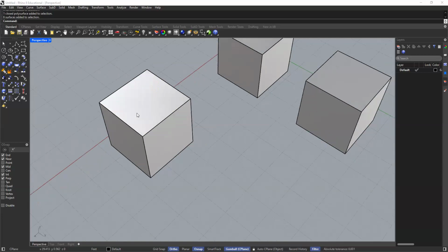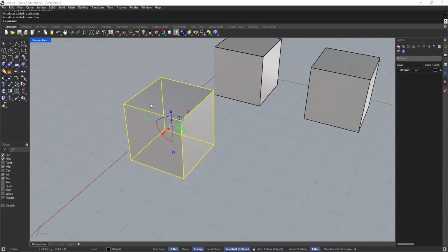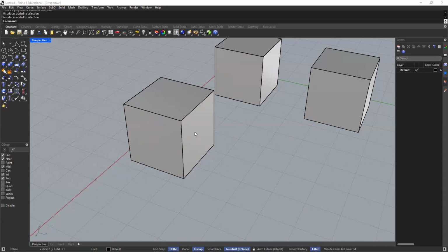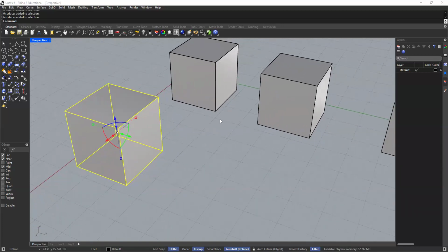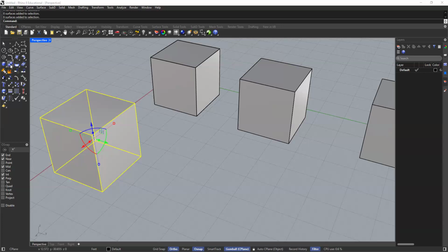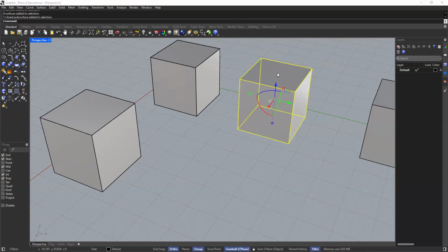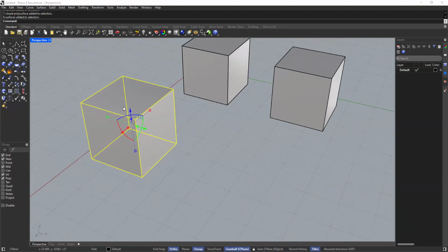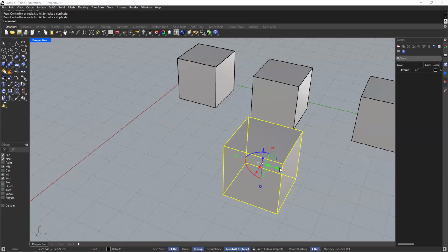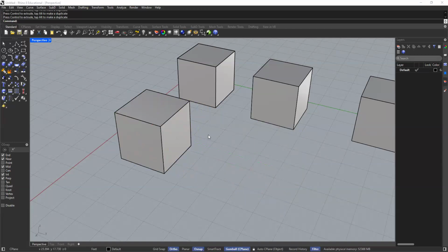However, what we ended up just doing right now with grouping is we grouped 6 surfaces into one, so that when I click on it, it selects 6 surfaces. That is not the same as turning it into a poly surface using the Boolean union command, okay? Because this is still 6 sheets of paper taped together at the seams. This is an actual solid object. Okay, so grouping does not turn your object into a poly surface. Grouping just groups all of the surfaces into one, so that makes it easy for you to just kind of move this around. Okay, that's it.